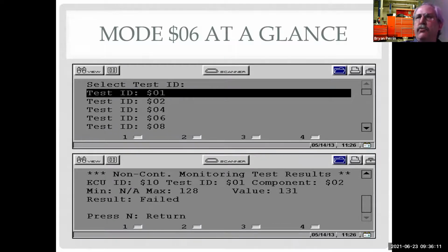So at least now you know that there's this feature in there, that if someone says, oh, you need a catalytic converter, you can go, well, how were the test results when the computer tested it to get my 420 code? If the person gives you a blank look, maybe you shouldn't be going to that mechanic, because that clearly shows that they don't know how to get the test results. So what, they pull your 420 code and tell you you need a catalytic converter? Right? I mean, seriously. So now you know what questions to ask.